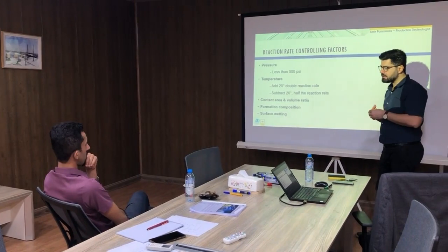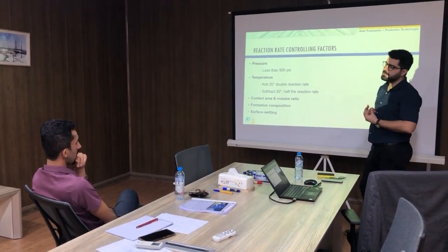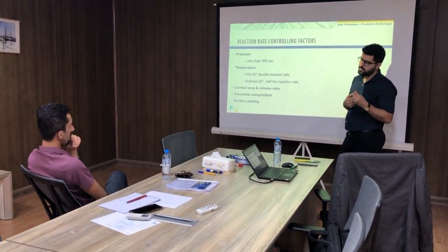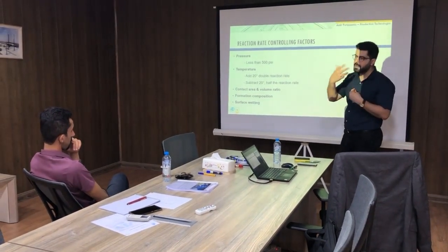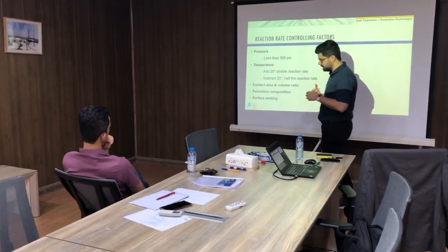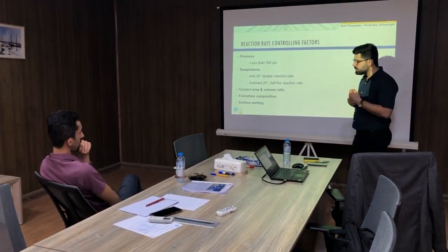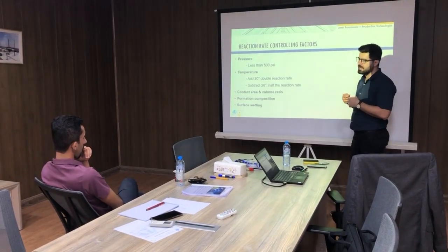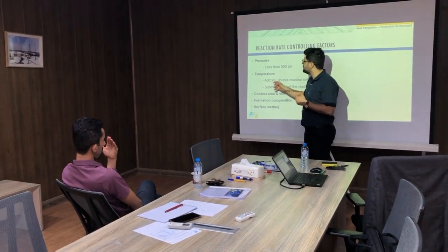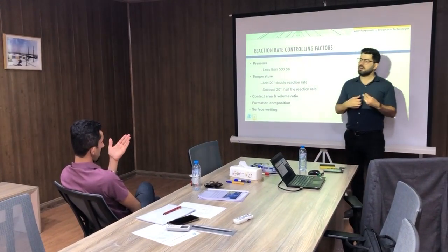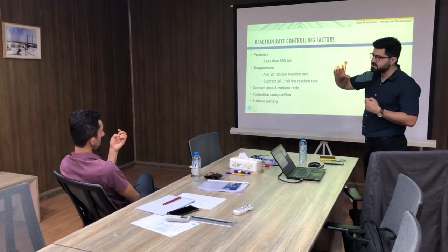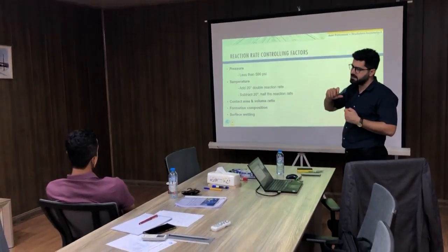For some cases, if your reservoir is a high temperature, high pressure reservoir, just like Yama one, you should know it and consider it in designs. Because of that, you have a high reaction rate. So because of the high reaction rate, you should consider it by increasing the concentration of your acidizing.